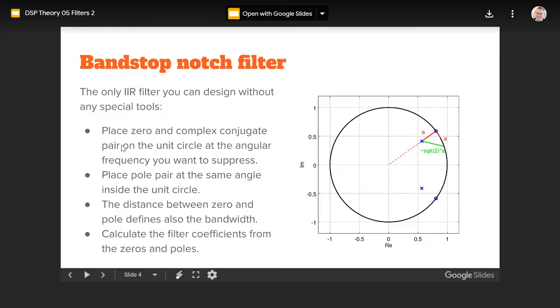How about your microcontroller? It has about 5% accuracy on the crystal frequency, unless you put it in an oven, an external oscillator in an oven. So basically heat balance it, then you may actually get into a couple of ppm with good crystals. But anyways, in a perfect world it works.